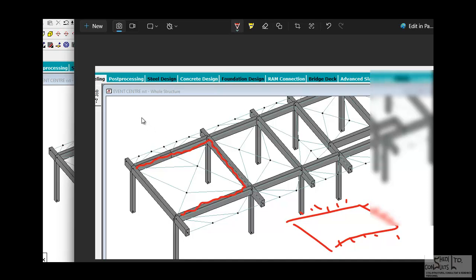For those who have done plastic analysis, you have the static approach, and then you have the virtual work method, where the external work done by the external load is equal to the internal work done by the plastic hinges. That's not the conversation. So yield lines form at the location of the support, and then at the intersection between the supports. This is how yield lines are formed when the slab is about to fail.